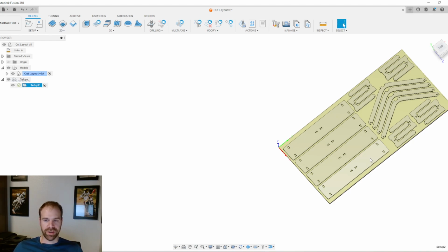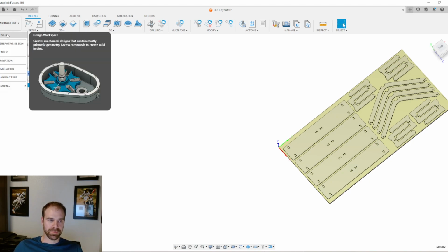Maybe you tripped a circuit breaker because you're driving it too hard. Maybe it plowed through the material too fast and it just couldn't keep up and it stalled out. Maybe you had to hit the E-stop, and when you hit the E-stop it loses its position. So it's a really good idea to have reference points drilled into your plywood before you start cutting.